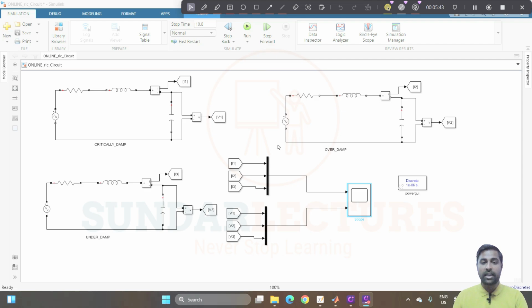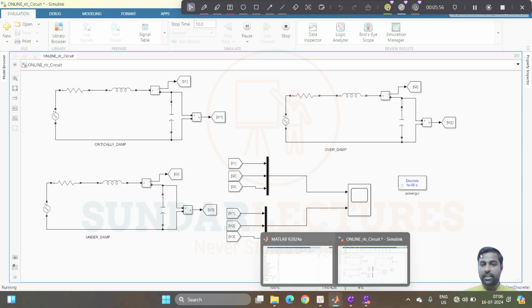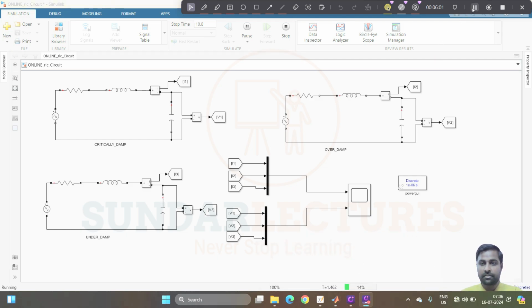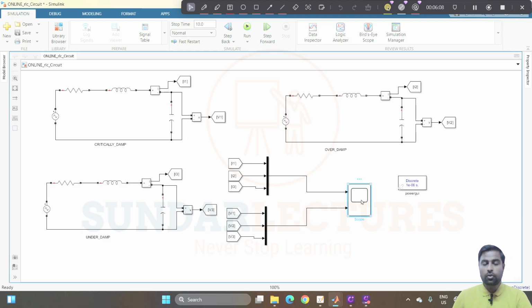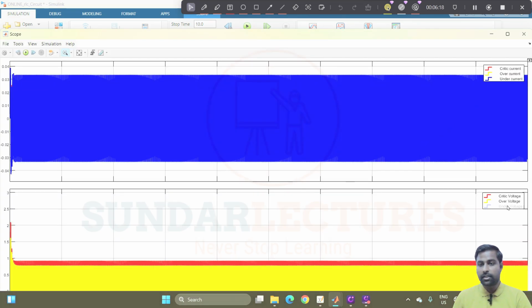Now you come here. Now what we need to do, we need to execute this circuit. For that, you go here, click this run, and you can see that it is compiling and it is running here. So wait till 100%, and now you see it is completed 100%. Now you go to the scope, double click on the scope. Yes, that's all. First of all, you will get all the values.